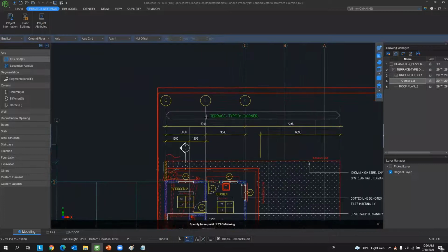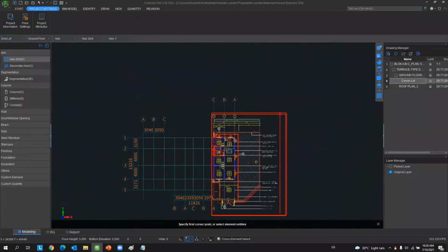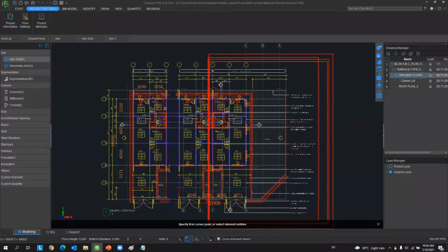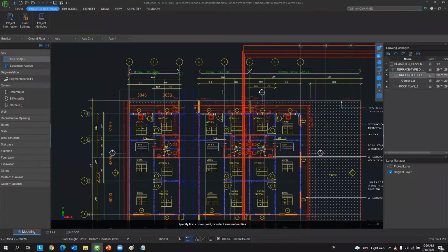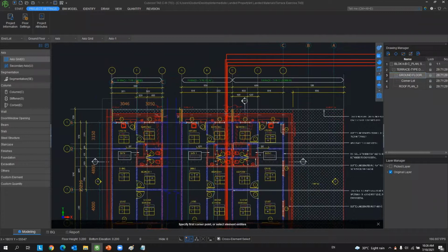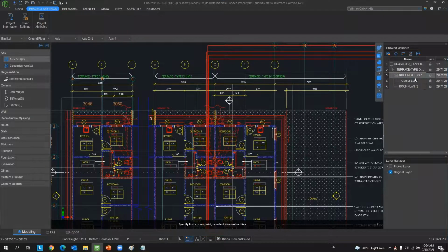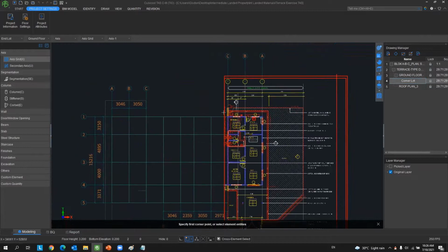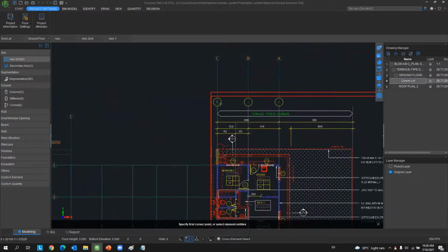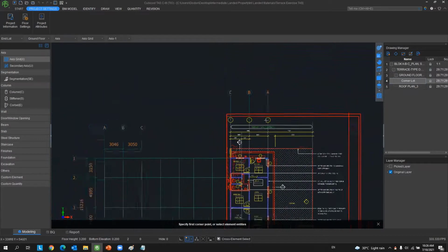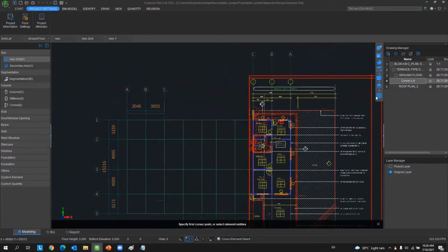So that later when I do the model, it won't have overlapping for the part of the wall, right? So from here, first you have the drawing with the corner, intermediate, and end lot. To avoid this overlapping issue for this particular part of the wall, I split the drawing to become a corner lot. I have a corner lot, and then I relocate it as per my axis grid line, C, B, A. So this is the first step.